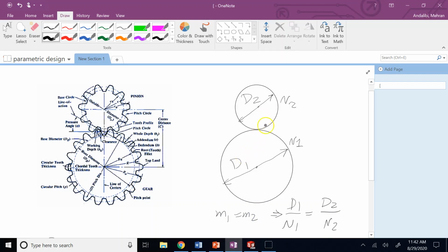Otherwise, they don't work. And probably you experienced that, or you will experience that in your EGR 101 course, where you wanted to put gears together and, let's say, reduce the RPM or transfer the rotational power. You found that not all two gears in the Lego kit will mesh together, right? Only those that have the same modulus. So let's say here, this top gear has, as far as I can see, 3, 6, 11 teeth. So this guy has 11 apparently.